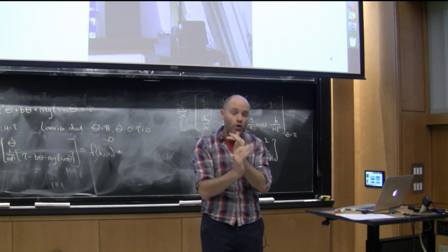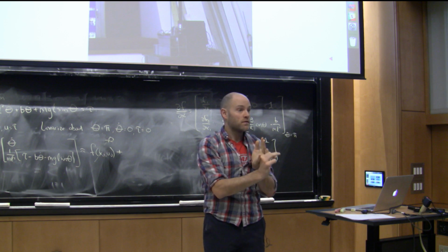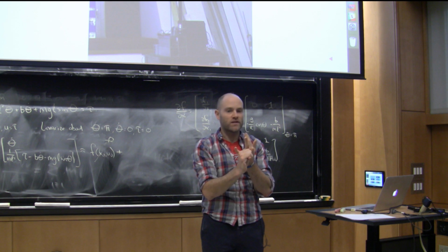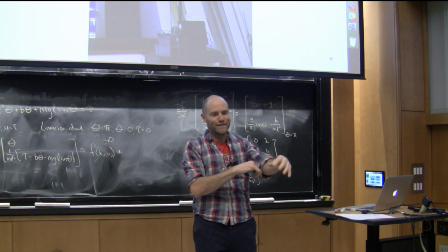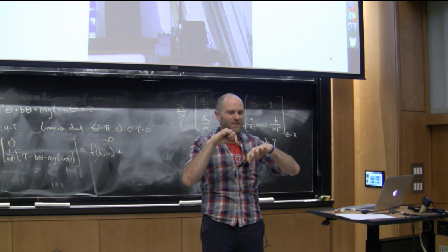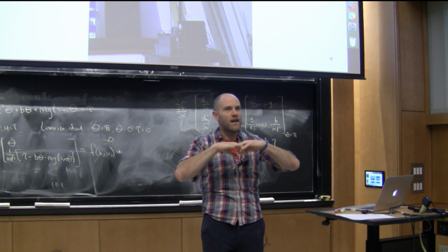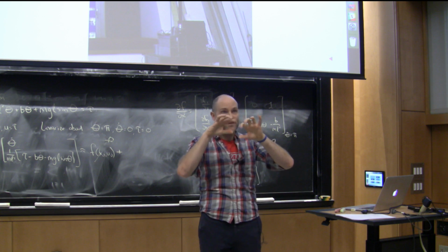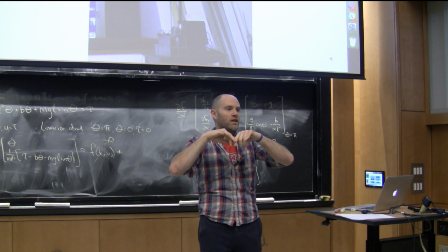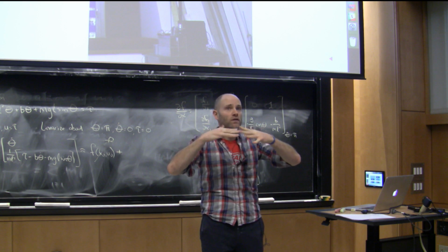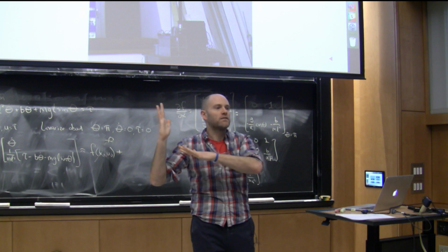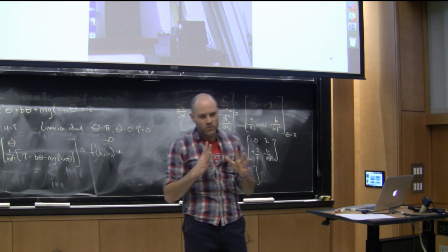Okay. What's another thing that could end up throwing it off? So we talked about encoder offsets, which I think are probably the second biggest one. Lag. There's two ways you could have lag that matter. One is that, especially because we use message passing in robot stuff, we send a message and there's some latency between our command getting to the actuator, and so that adds some lag, but that's pretty small. The lag that I worry about more is that I have a state estimator running, which is observing potentially noisy inputs and converging fairly quickly to the observed output, but that introduces some lag, which is not negligible in the time constant. The goal is to sample your sensors fast enough that the dynamics of your state estimator are much faster than the dynamics of your plant, of your robot, right? And we try to accomplish that, but it's not perfect.